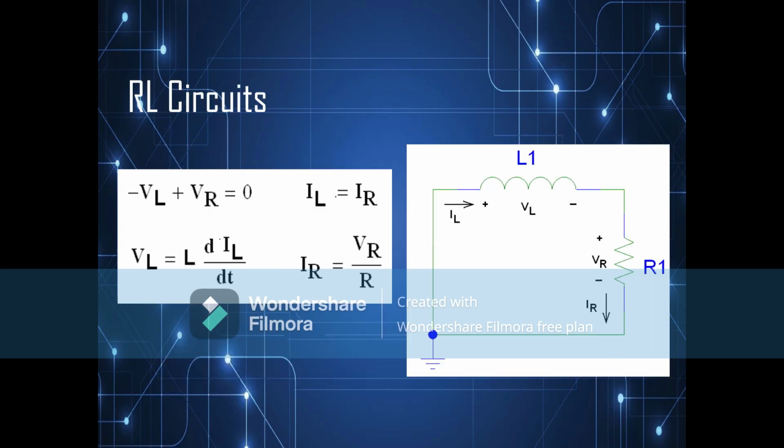RL circuits. Negative VL plus VR is equal to 0. IL is equal to IR. VL is equal to L dIL over dt. IR is equal to VR over R.